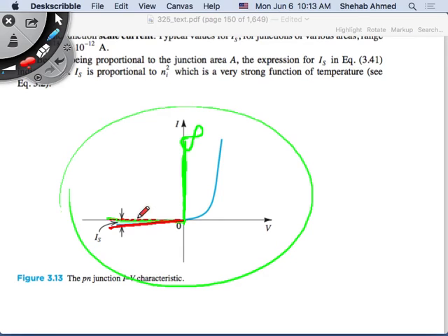And that's why, okay, so first we went from the ideal model, zero current in the reverse bias, infinite current in the forward bias, right? Then we said that there's another model where I have a fixed forward voltage. This fixed forward voltage, we set it at 0.7 volts. So we said that it's a piecewise linear model where I have a linear relationship in the reverse bias.